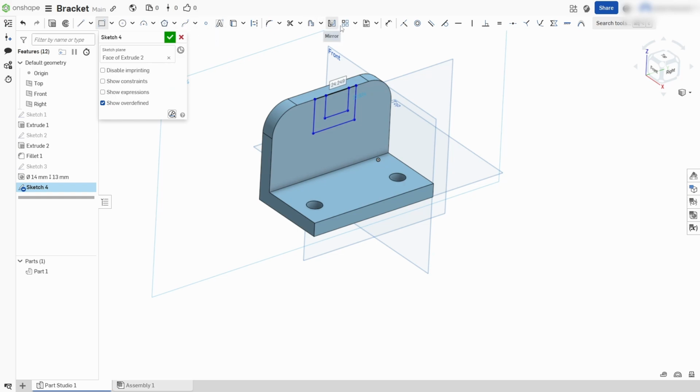Don't close it out. Actually, let's go dimension this guy. So he is 18 millimeters wide in here. Okay, and then we have 10 millimeters each width here. 10, and then another 10. Okay, and we definitely want to have this centered. So to center this, it was 126 to the center. Let's check that. So we're going to take a dimension here to hopefully that.